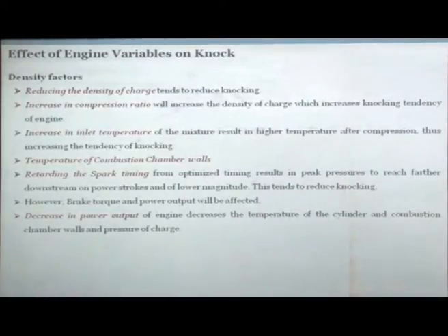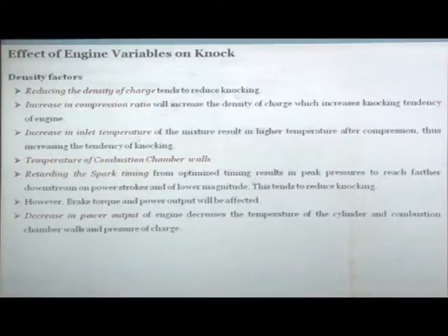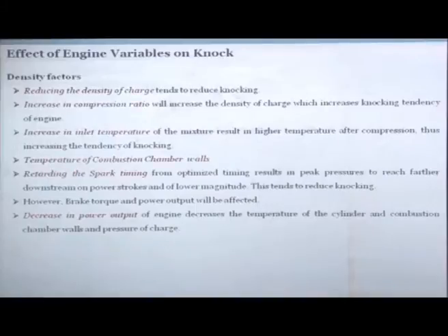Okay. Then increase in the compression ratio. What will be the effect of the compression ratio? It will increase the density of the charge, which is going to increase the knocking tendency. Increase in the inlet temperature of the mixture results in a higher temperature after compression, and this will also increase the tendency of ignition. So you should try to keep the intake charge as cool as possible. Then temperature of the combustion chamber walls. If temperature of the combustion chamber walls goes up, this will also increase the tendency of knocking.